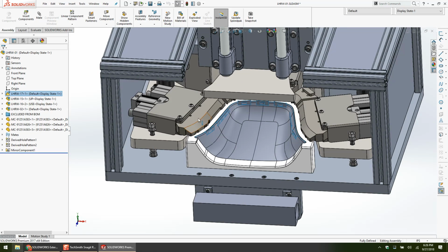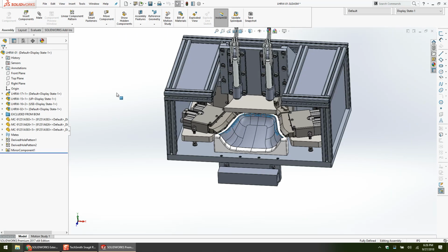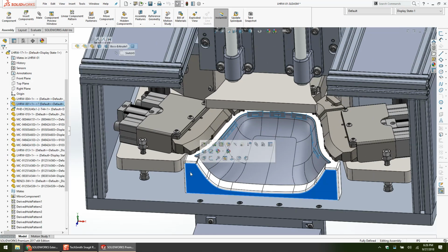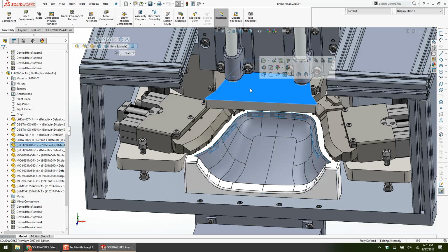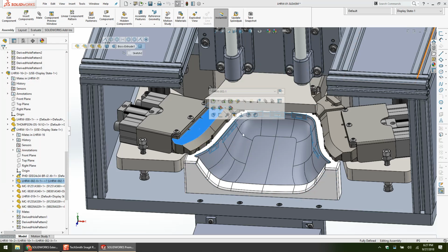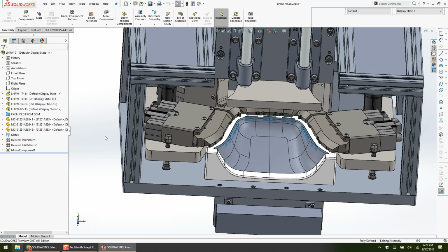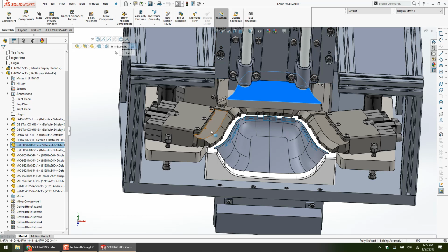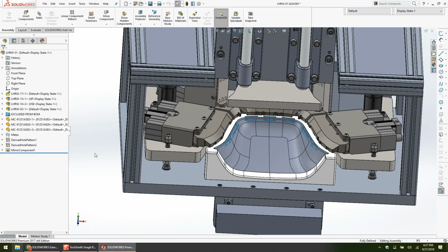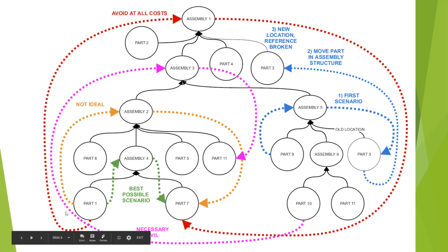But anyway, the first thing I want to demonstrate here is in this particular design, at what level do I have this plate and this nest and these jaws all external referencing the customer part? They're all fundamentally at different levels of the assembly here. This has to go up and down, these have to go in and out, the nest has to be stationary. There's no singular subassembly or no easy way in the top level design to say, this is where I'm going to construct all my external references. We want these loops to be as small and short and concise as possible.